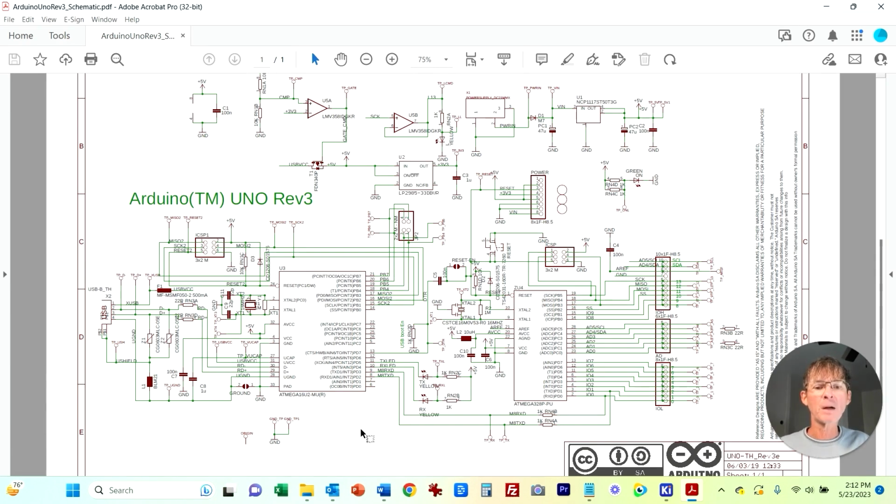Okay, so we have this microcontroller we talked about. This is the main microcontroller. You have all the support circuitry here. This microcontroller has its various support circuitry. You have the USB port that comes in. It does two things. It provides power, so it provides a 5-volt signal, and then it also has two data lines that tie into this microcontroller for the communication. And then, of course, there's a ground connection.